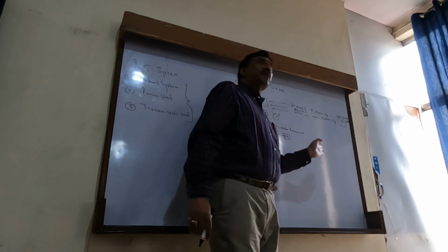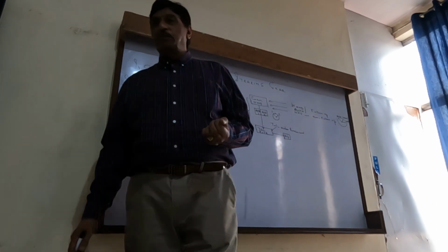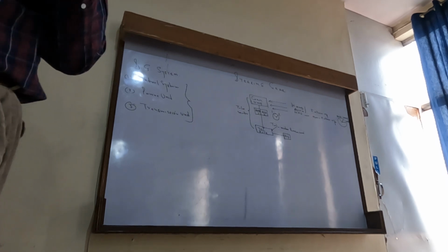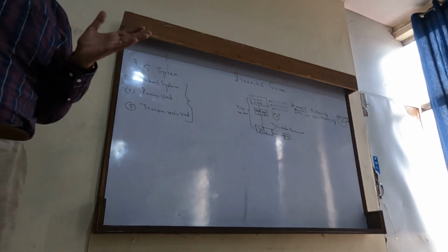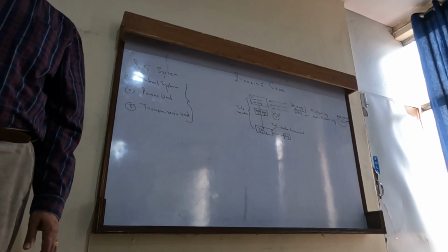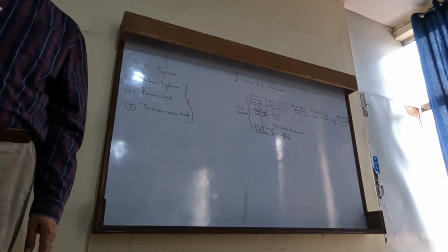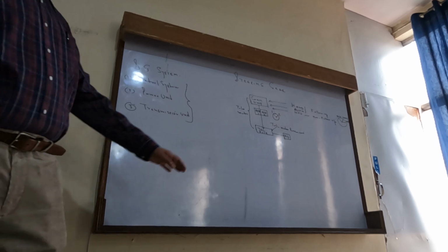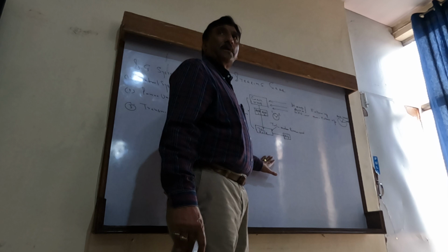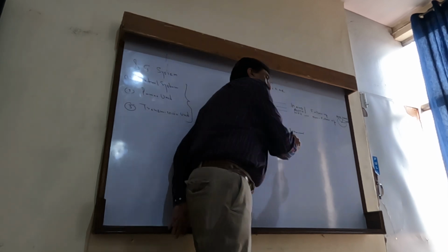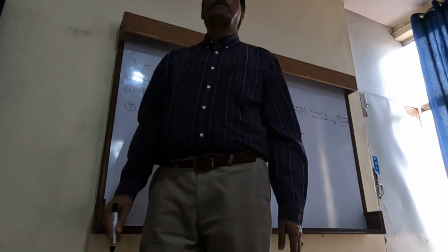Now hunting gear is a system which we call a control and shut off system. Control means it will control till you achieve the required angle or required helm. This wire, this lever, this feedback is coming from the telemotor. The telemotor receiver is giving a signal to the hunting gear.